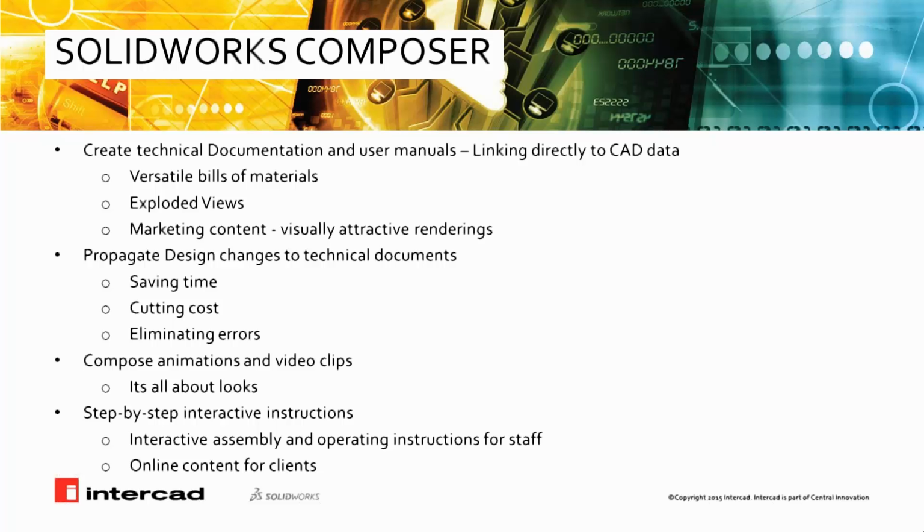Okay. Now the good thing about using the raw CAD data that comes out of the CAD system is that you can take advantage of all of the detail that's in the design, as well as the metadata, things like part numbers, descriptions of components, and any other data that is used in bill of materials, for example. And this is all data that will be needed to create technical documentation of our designs, which is what Composer is all about.